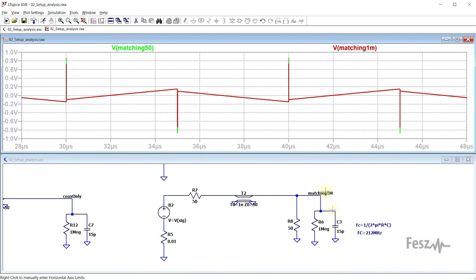So therefore, the bandwidth of this setup is limited. With my particular scope's parameters, this should yield a corner frequency of around 212 MHz, which is just slightly above the device's built-in bandwidth limit. Therefore, this should not present any major limitations.